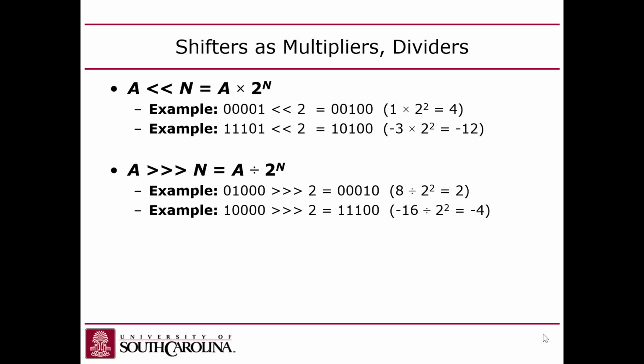Which is 13 divided by 2, but you round down. And the reason you round down is because you lost that 1 bit there, right? That represented the 0.5. That would have normally been shifted to the right of the decimal point, but if we don't have a bit position there, it gets shifted off, it just gets dropped, right? If we don't have any fractional bits. Make sense? If you shift it by 2, so this would be 0,